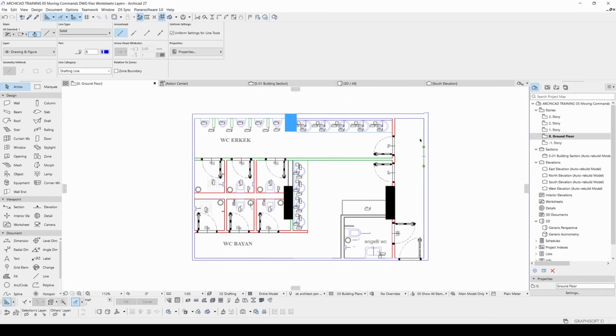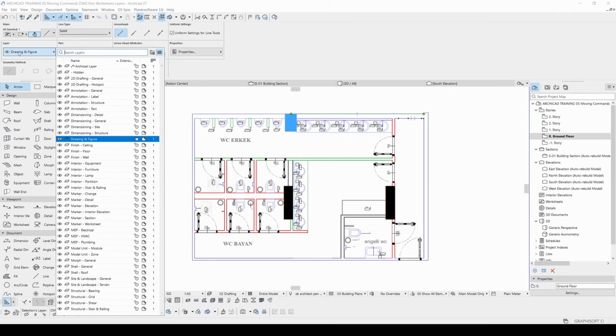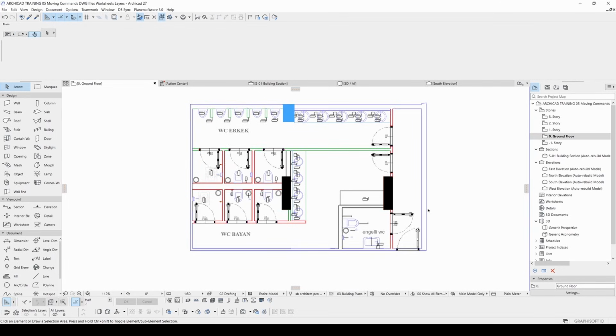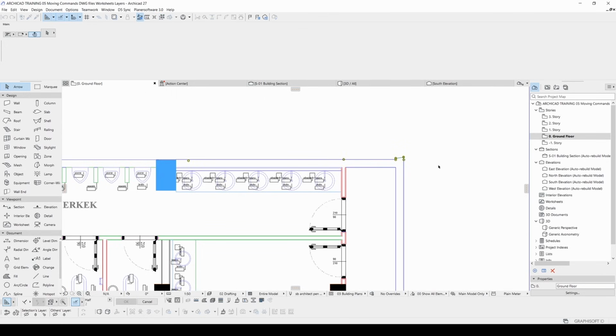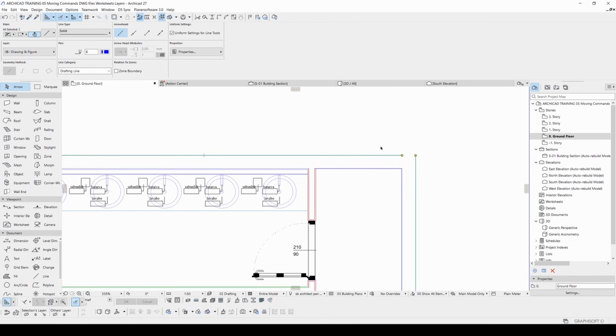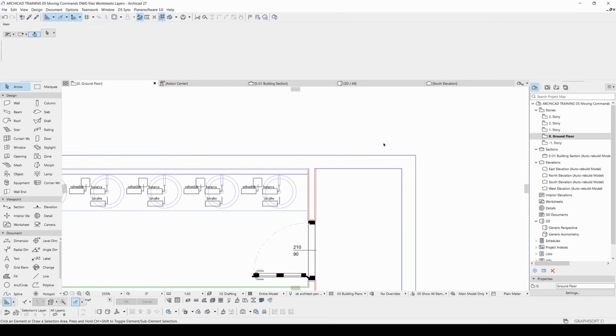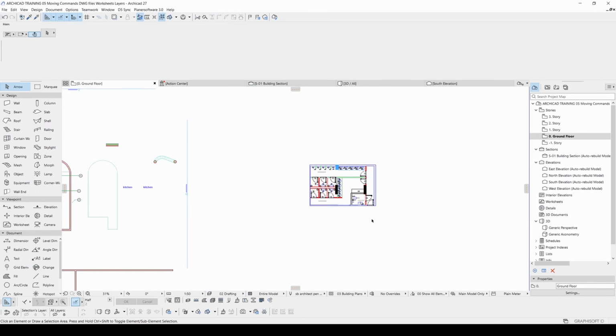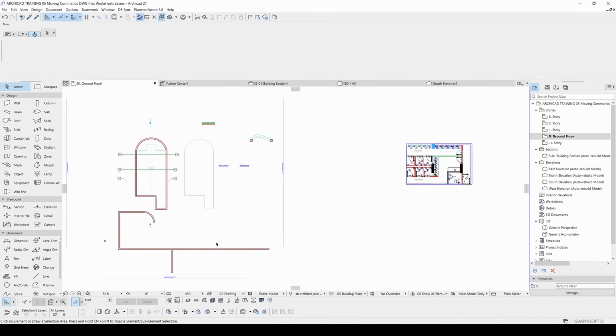And now we can click each different line. And this drawing figure is in the original Archicad layer. You can even continue editing as we did in the first lesson. I'm going to select these two and intersect them, for instance. Or I can just use this as reference.